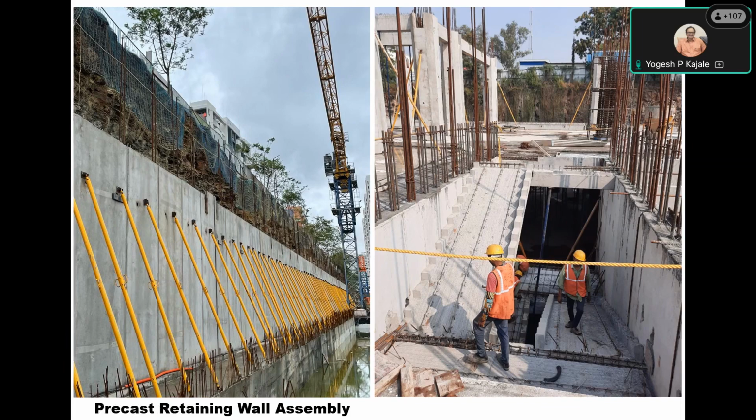in water tanks we require a leak proof construction. Now to get that leak proof construction, for each and every joint we emphasize that it is concrete, in situ stitching concrete, cast in situ concrete. So with this hollow core method, we are able to achieve that water tightness. Of course, the waterproofing methods are more or less the same, rather exactly the same, as what we use for cast in situ construction.